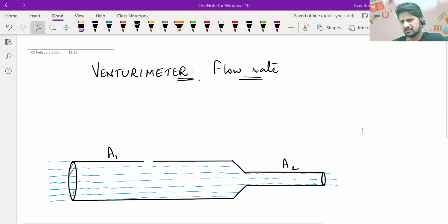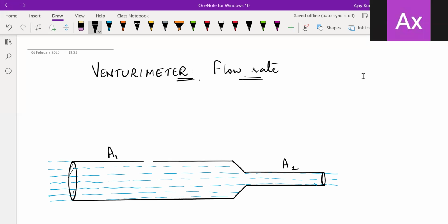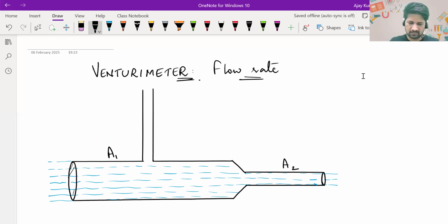Fine. Usually, when there is flow inside a pipe, pressure will be greater than atmospheric pressure, but good that you considered that factor also. So let's assume the pressure inside is more than atmospheric pressure, so the liquid will have a tendency to flow out. Imagine inserting a vertical tube here, like wherever this hole is made, imagine inserting a straw there. Depending on the pressure of the fluid inside the pipe, it will rise to a certain height in this straw. Let's say it rises to this height and settles.